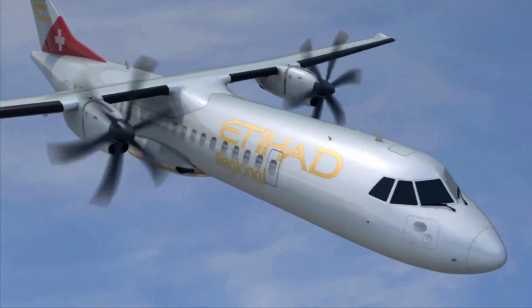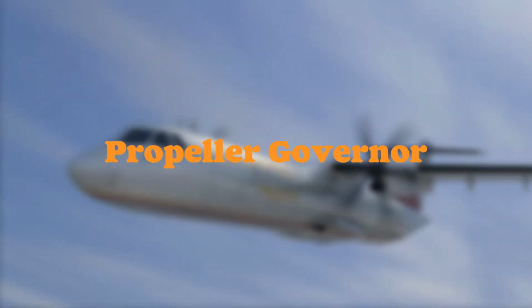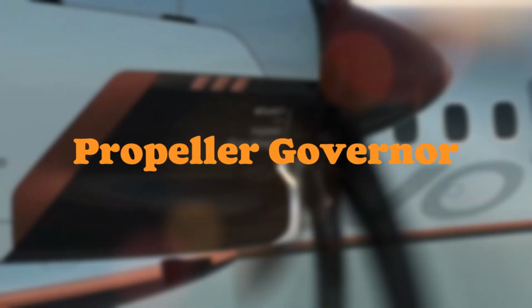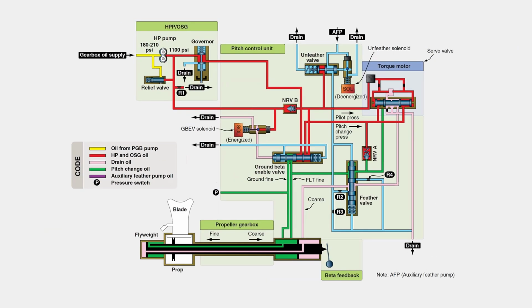Welcome to Aero Guide. In this video, we'll explore the aircraft propeller governor, a critical component in constant speed propeller systems that manages engine RPM automatically. Let's dive in. A propeller governor is an engine RPM sensing device combined with a high-pressure oil pump.